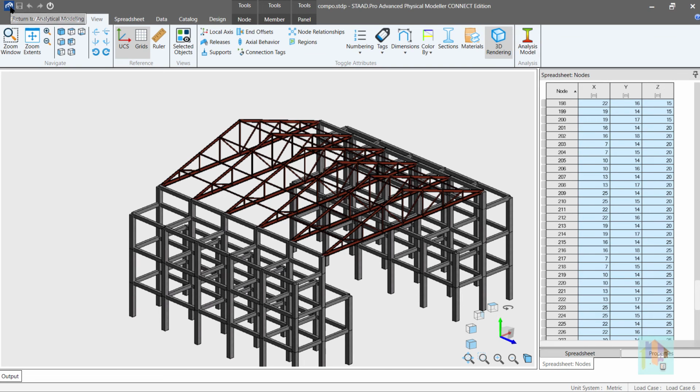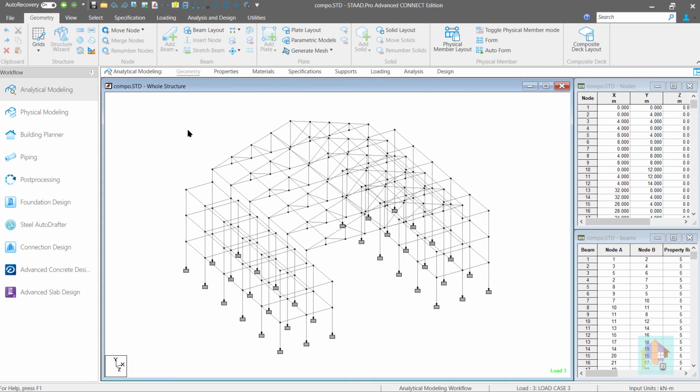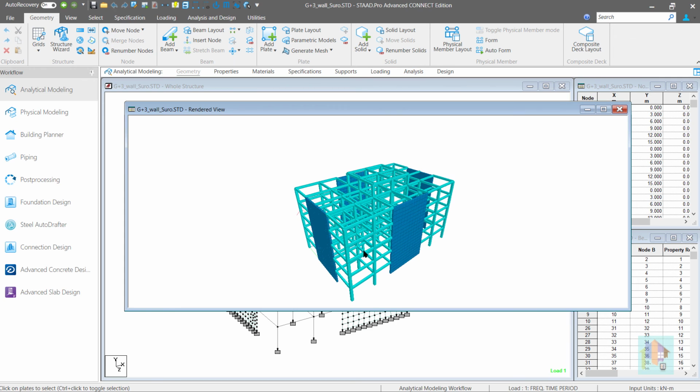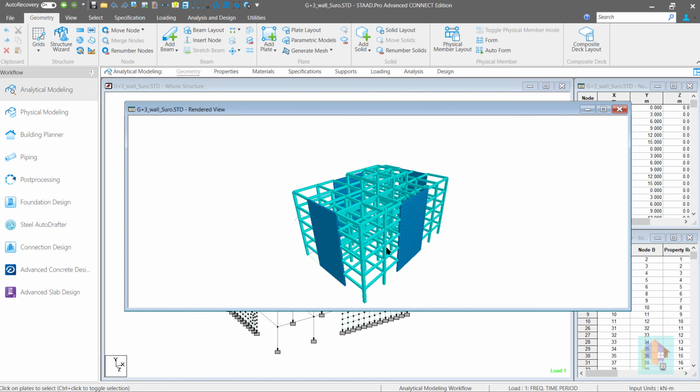Though these models are different, there is one similarity. No walls are modeled in any of these structures. For any high-rise building, it is quite common and also required to include several shear walls in different locations and directions. When you introduce a shear wall, the load transfer path and structural resistance to lateral force is modified.